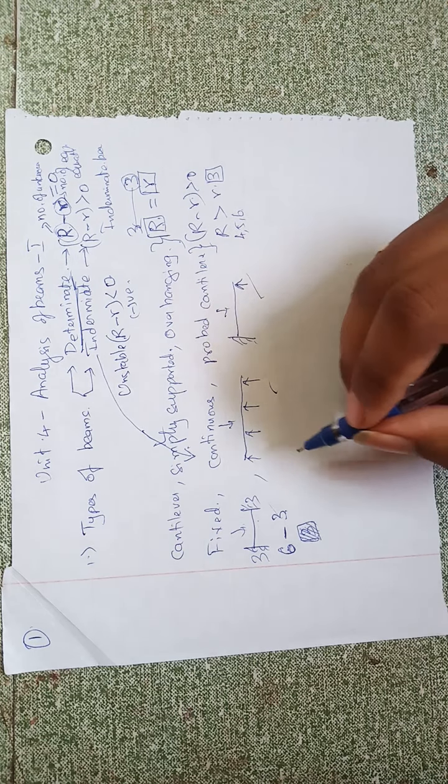Then for this continuous beam, it has four reactions. So you will have 4 minus the equilibrium equations, which here is 2. Why 2? You have summation of moment equal to 0, one equation, and summation of vertical forces equal to 0. You do not have any horizontal forces. Since that equation is ruled out, 4 minus 2 here will be 2. In case it is a hinged support here, you will have 2 reaction forces here, then the equilibrium equations are 3 and total reactions are 5. So 5 minus 3 is 2. There are 2 extra unknowns, so 2 redundancy.